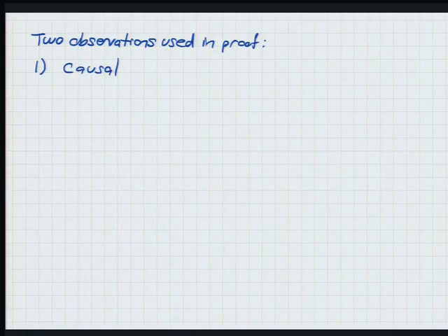So what kind of region of convergence do we associate with right-sided signals? For example, 1 over S plus A. Remember the example from last time? 1 over S plus A goes with e to the negative at u of t, right? What is the ROC? Greater than minus A. So we saw last time in examples that it's always to the right of the pole. The pole will be at most on the boundary. It can't be inside the ROC because it's infinity at the pole, right? So causality